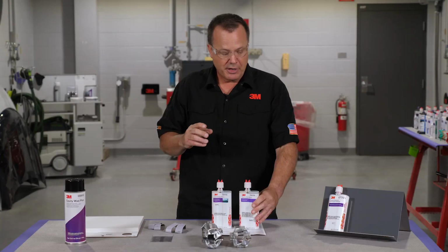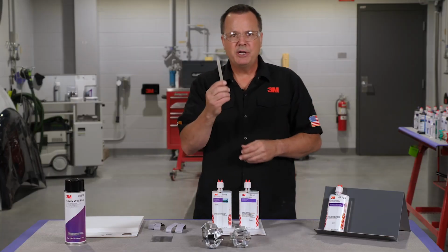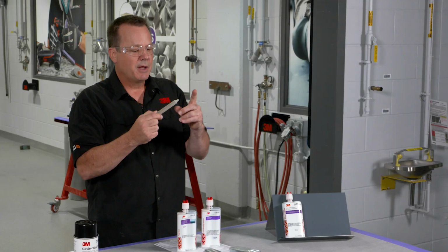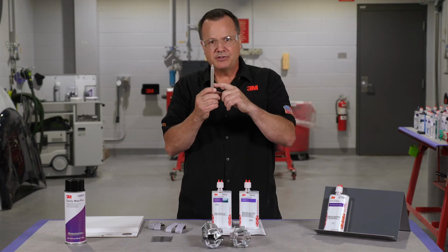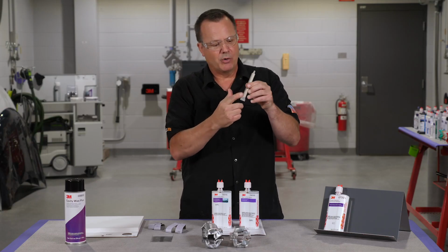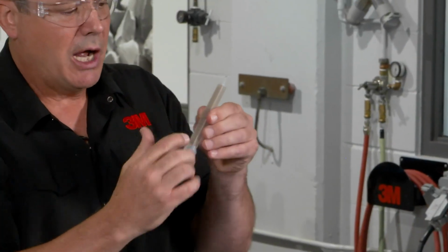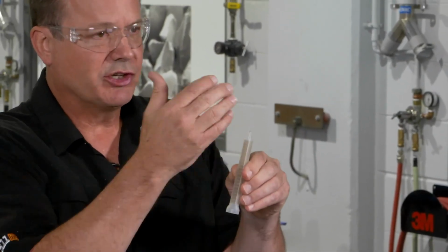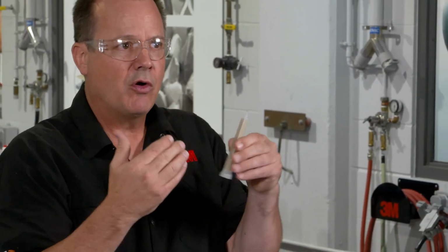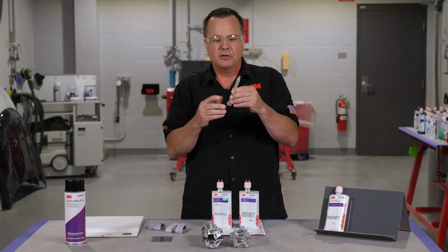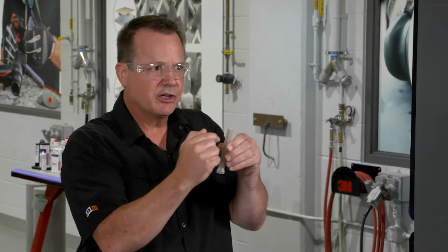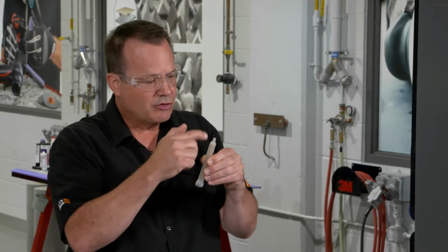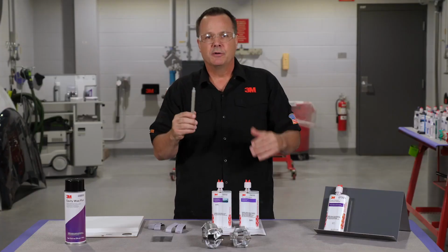Now, the other question we get is, why do we need to purge some material out after we've equalized the cartridge? And the reason is that when this tip is empty and we're pushing product through it, there's no back pressure on the material down here. It's just air above it, so it tends to flow through without going through that mixer very thoroughly. So once we fill this about halfway, now there's back pressure that forces it through that mixer a lot better. So that's why we want to just run out a couple inches of product before we start to apply it